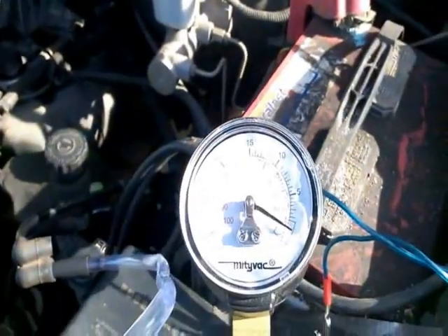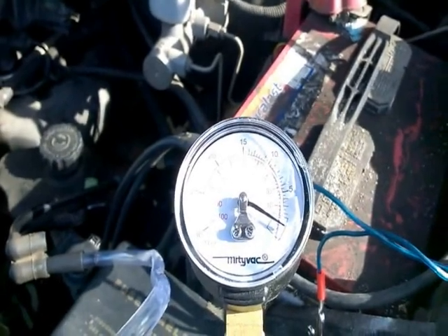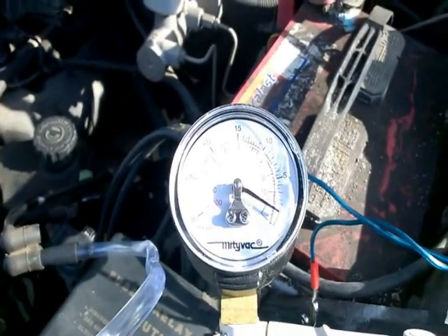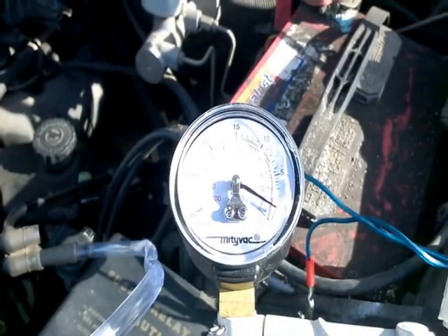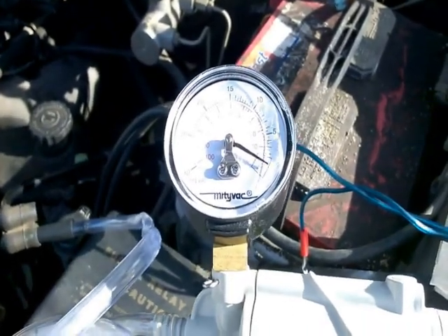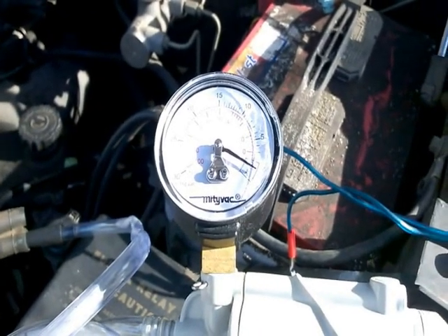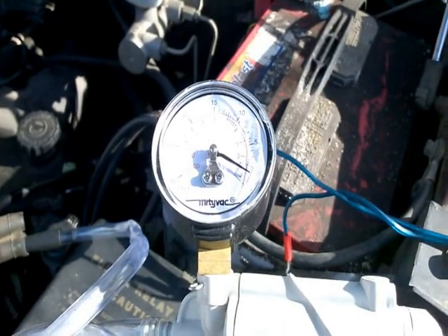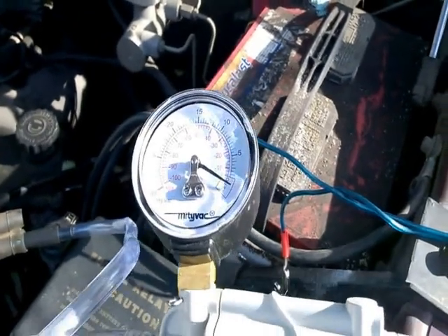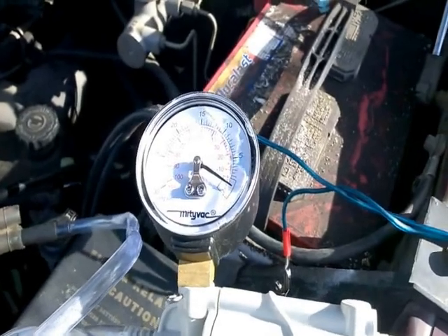Oh, and it's normal that the vacuum gauge does not go up. That's normal, so don't freak out or anything. Just apply 3 to 5 strokes and the vacuum should close the switch on the natural vacuum leak detection pump. So here we go. I'm gonna stroke it at least 5 times, and that should create that 1 inch.